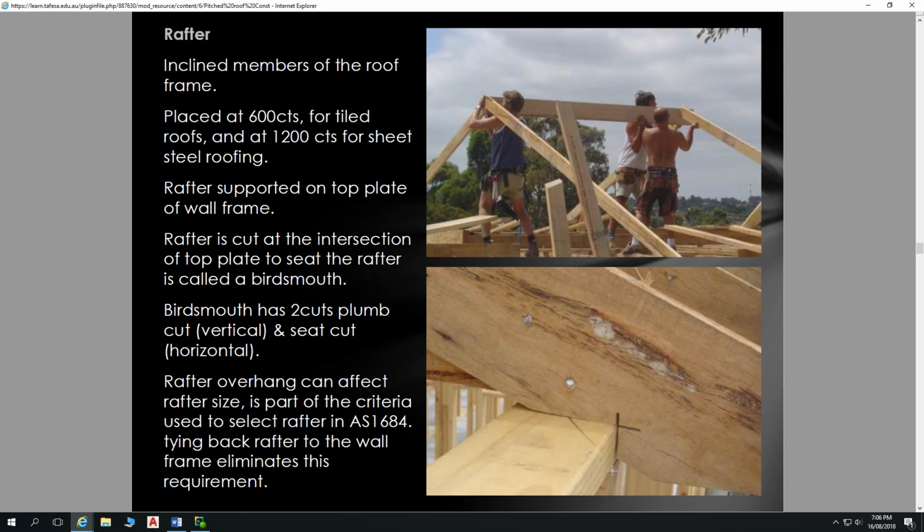Our bottom plate is screwed into our slab, with masonry anchors into slab, being Dynabolts or blue tip screws. So the wind acts on that sheeting on the roof and sucks it, and so everything is tied all the way through that frame right to the ground to transfer that load into the slab.